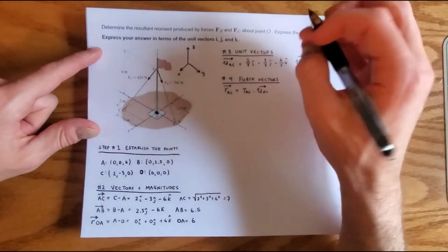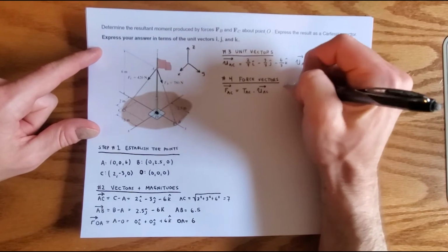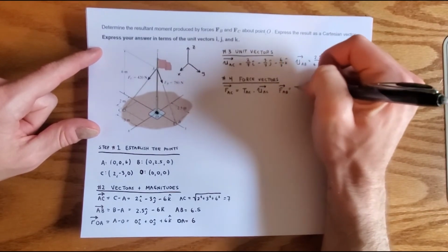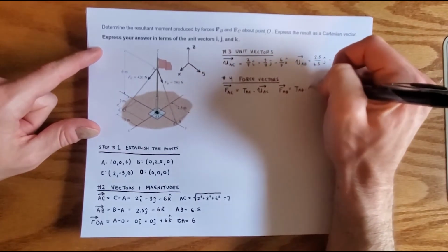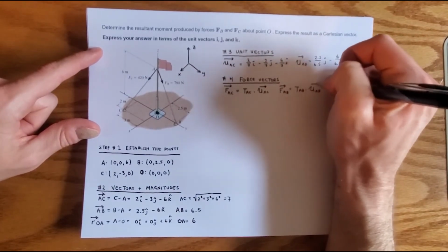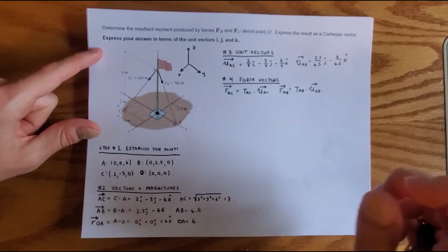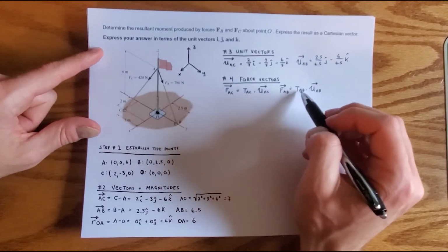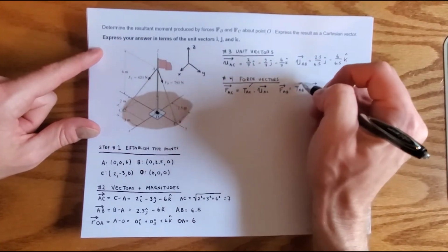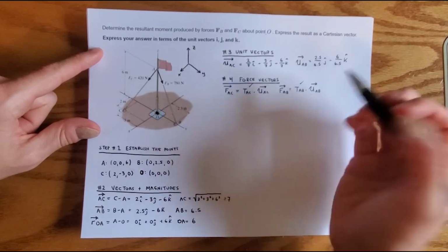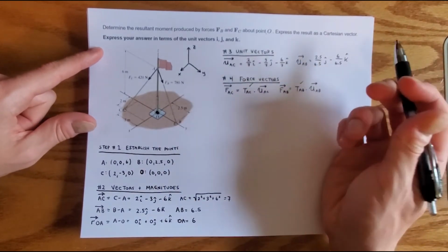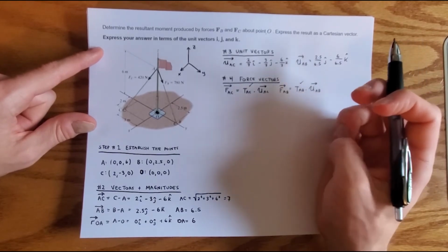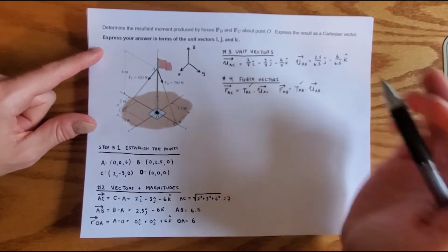We've got TAC here. And now what we also are going to have is the force of AB, which is equal to tension AB times the unit vector of AB as well, which is what we have up above. So remember, in the previous problems, we were trying to solve for TAC and TAB, but in this case, these are given. So we're not solving for those. And we have the unit vectors already. The thing that we're going to be trying to figure out is more or less, what are the moments? So how do we go about doing that?